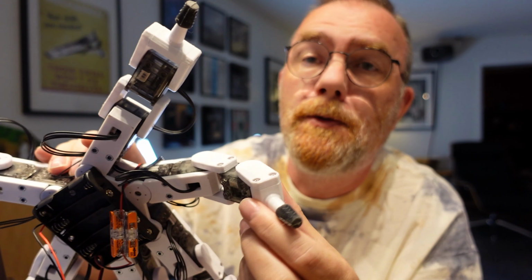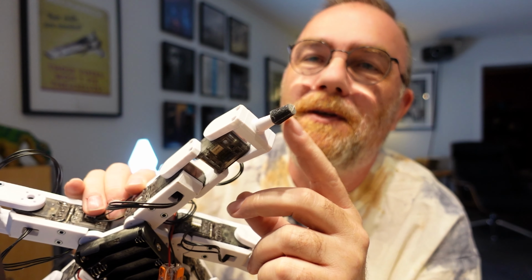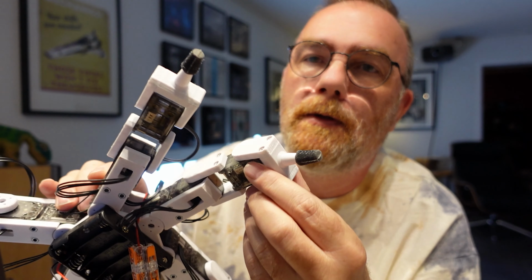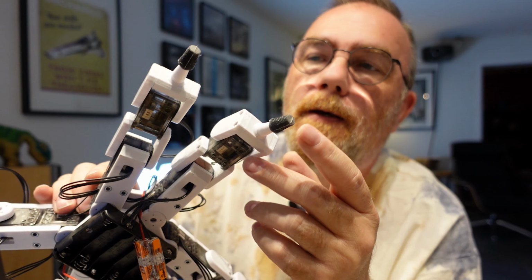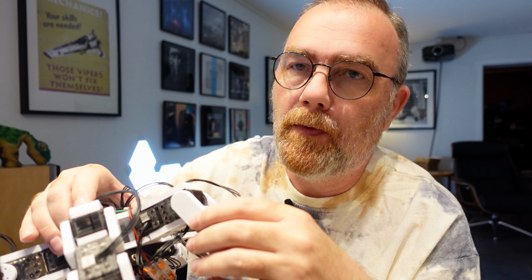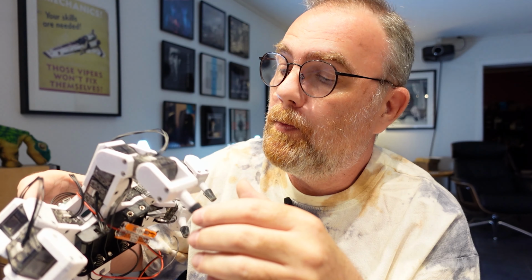You probably noticed this clicking noise that increased towards the end of the previous segment. That noise got old really quickly, so I decided to make some shoes, shall we say, for the end effectors. These are cast in really smooth rubber, so I used Dragon Skin 10. That reduces the noise, and it also prevents the hexapod from sliding around on my desktop.